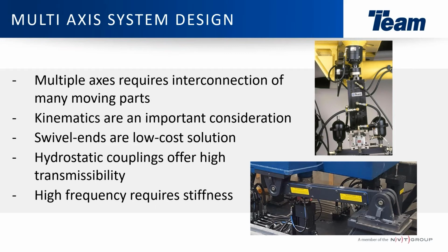A better solution is using hydrostatic couplings, basically replacing these greased swivel ends here. The hydrostatic couplings offer high transmissibility, which means the forces and stresses that go through from the test object into the actuator are transmitted 100%. There is no backlash, and you can realize a much higher frequency response. Now they do add a little bit more design criteria in there.